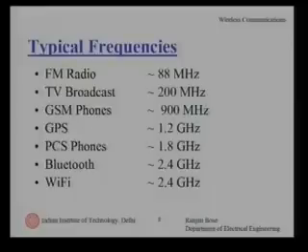Wi-Fi, 802.11b, works at 2.4 gigahertz. 2.4 gigahertz has been a favorite band recently because it is a free band. It is also known as the ISM band, right? It is given to the medical industry, to institutions, to scientific establishments to experiment with, and a lot of useful appliances have come out on this frequency band. We have a wireless lab here where most of the experiments have also been designed around 2.4 gigahertz, simply because we did not have to take any license. So, it is a license free band.